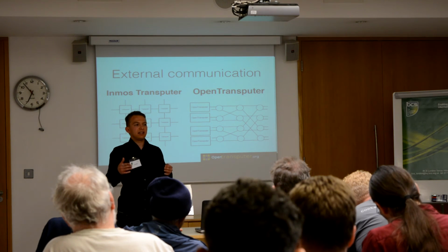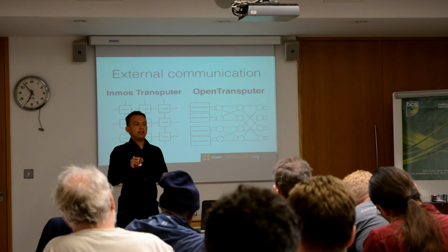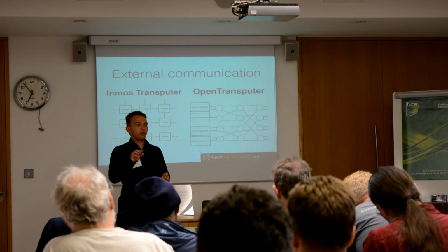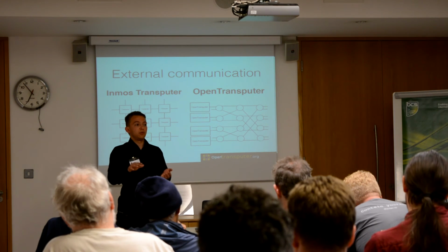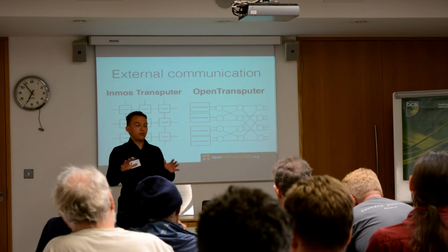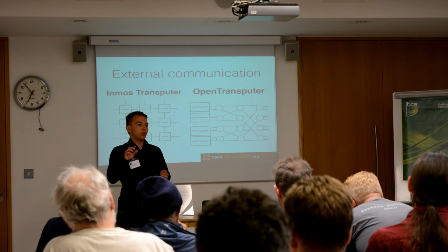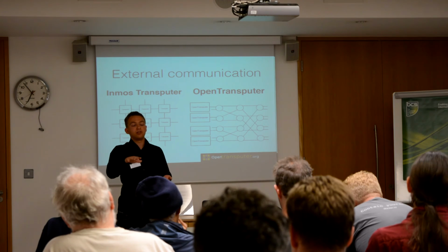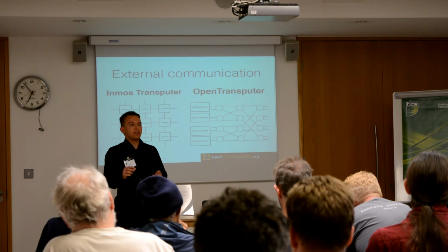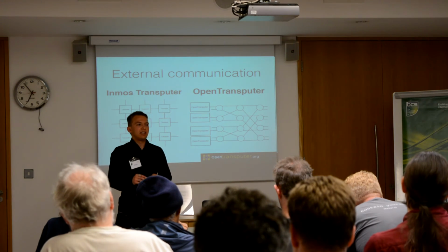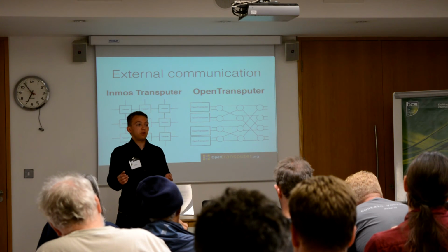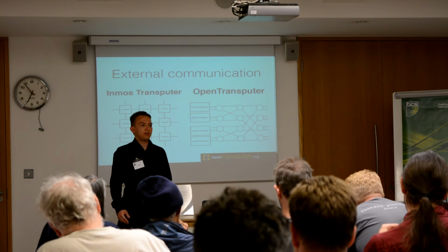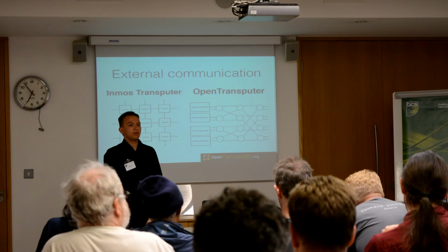So what this means, in practice, is it is very easy to scale an Occam program from one processor, one Transputer, or one OpenTransputer to 1,000 without any additional modifications to the hardware, or scale it down from 1,000 OpenTransputers back to one. Whereas with the XMOS architecture, you might have to do some fiddling if you want to go that large. So it's definitely possible, but you have to modify the software to make that happen.